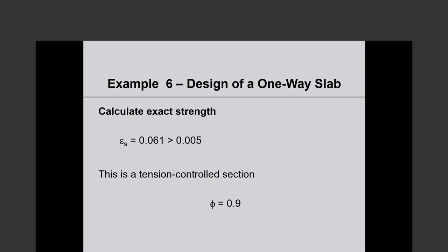Long-term deflection we estimate by multiplying the short-term deflection by a multiplier that I talked about. And the calculation of short-term or immediate deflection, ACI 318 specifically says, has to be based on cracked section. Remember I sub g, then I sub cr, and then I effective. So I effective is what you have to use in deflection calculation.